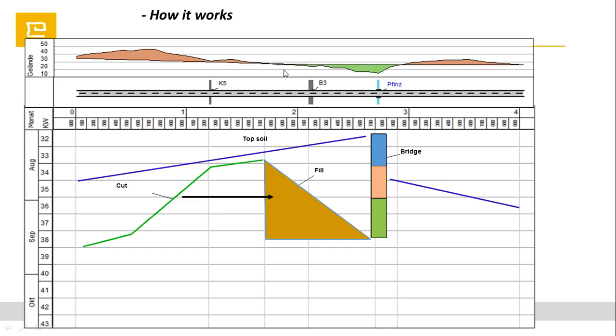And there are different types of activities. Topsoiling activities are different from cutting activities. The shape is different. The reason is that the cutting activity, even if we have one activity, is impacted by the quantity of the work in this area. What does it mean? Here is the area where we have cutting, and this is the first part, and you can see that it is taking only 3 days here.